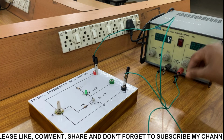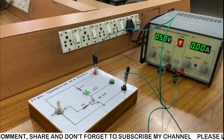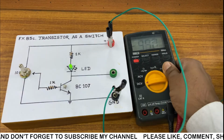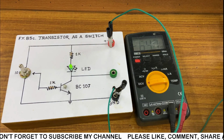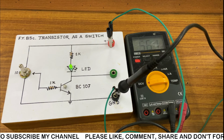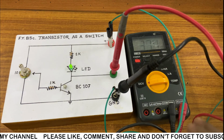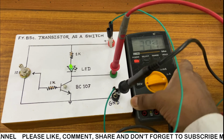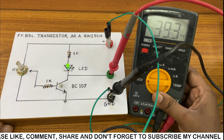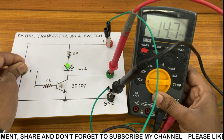Keep in mind, the current knob should be kept at the maximum position. You can see here the voltage at the output, which will be considered as logic 0 or logic 1. So I am putting the digital multimeter to measure the DC voltage. Here it is showing 39.3 millivolt, which means it is approximately equal to 0 volt.